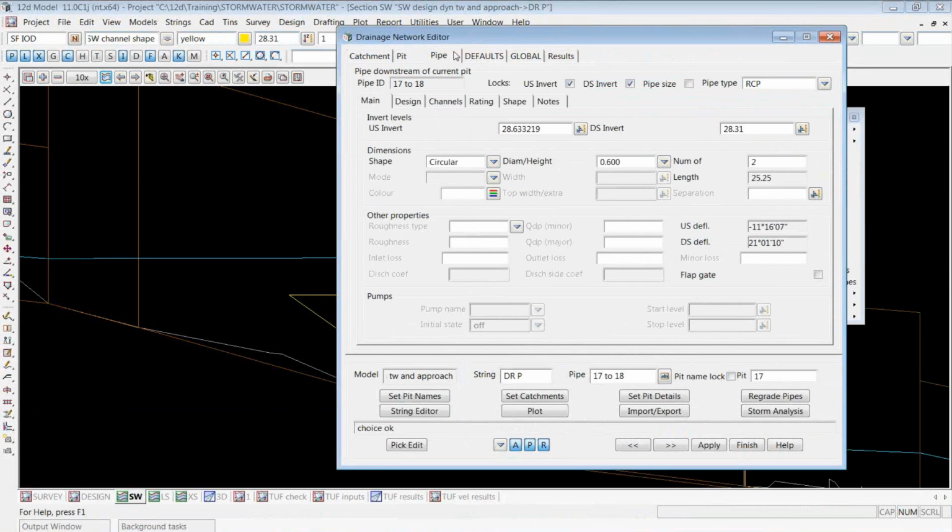But one of the options you can have with the pipe tab is you can come in and you can override those, both the inlet loss, the outlet loss, and you can put in additional minor loss. Each one of those uses the velocity at its corresponding position. So this is the entrance velocity times, so v squared over 2g times the loss, and an outlet and a minor loss using the velocity at the center. So with our culverts, we don't dynamically plot those for you, but you do have a place where you can put override values in. So I don't think that completely answers your question.